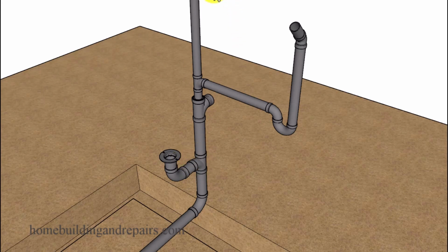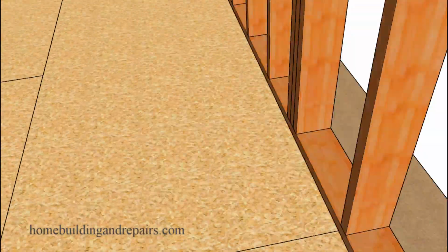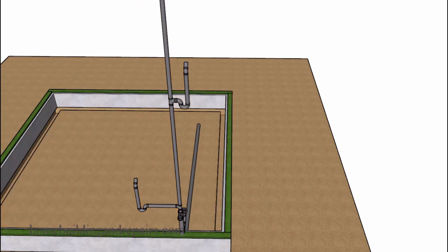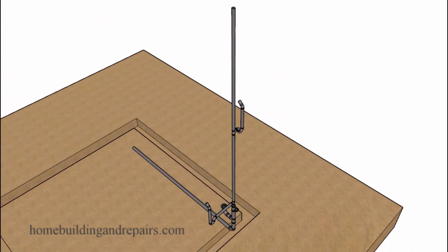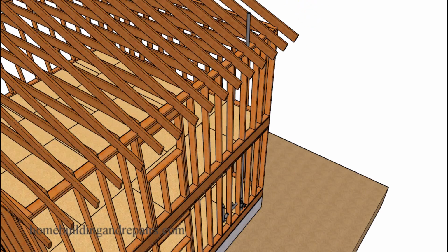And I do have other videos on wet venting if you need more information. And hopefully by now you're starting to get it. We cannot install another fixture on the floor above, because now the wet vent area would be going between the floors. The wet vent is now from here all the way down to the fitting where the toilet arm comes off. So let's wrap this video up by showing you what would be acceptable. And then of course it would be a dry vent pipe going in between the floors and not a wet vent.